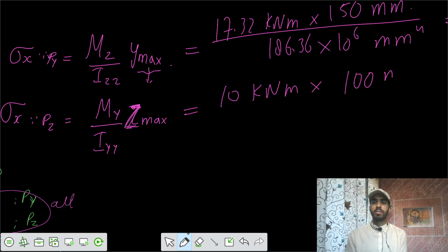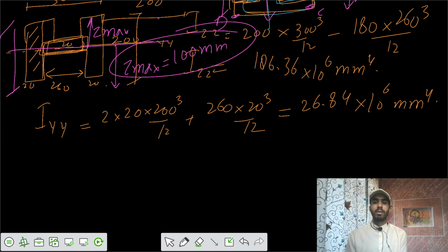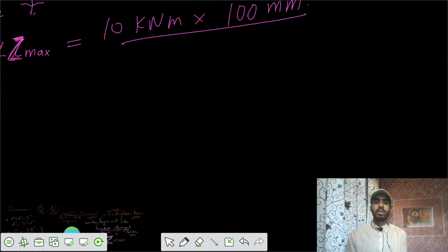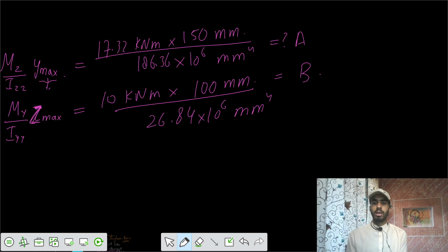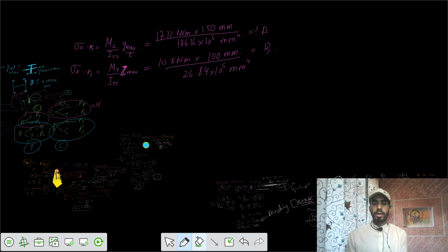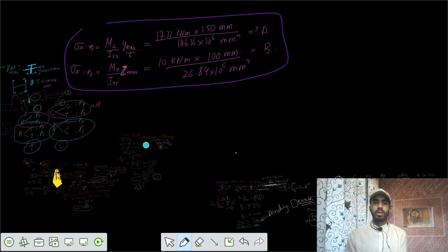Zmax was 100 mm, that is 200 by 2. And the value of Iyy was 26.84, I think, 26.84 × 10^6 mm^4. So you got a value of, say, A and a value of B. Now, this is only with magnitude. We don't know the sign yet, and now we are talking about the corners. This is the value of A and this is the value of B. So we got two stresses.